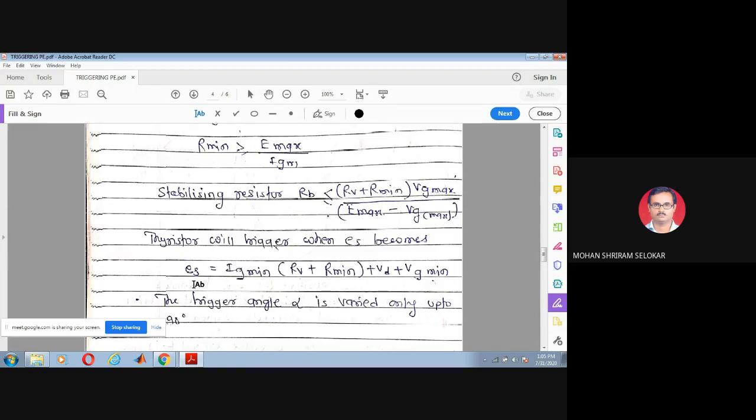Hello students. Yes, sir. I am saying one statement. Let me know, are you agree or not? My load voltage is inversely proportional to delay angle. If you look at the waveform, when the delay is more, the average value of load voltage will be less.